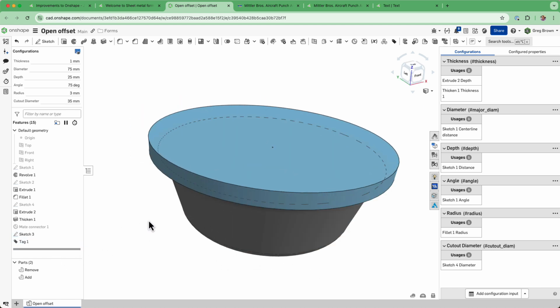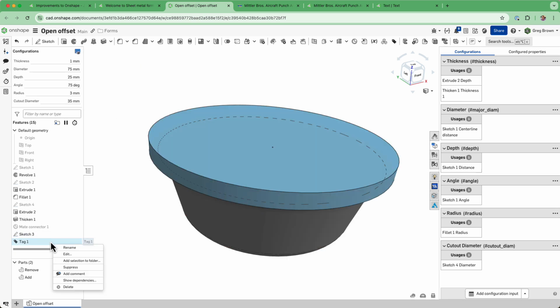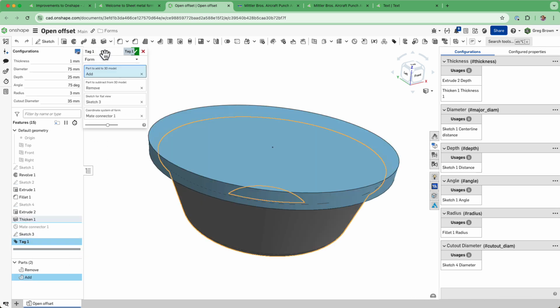And the last thing you do is create a tag, and a tag is the thing that designates it as a form feature. You'll see the tag up here. Previously, the tag was really just for the frame profile library, but now you can see there's the frame profile library and form library. Within the tag, there's a little bit of information, not much, that you need to provide.